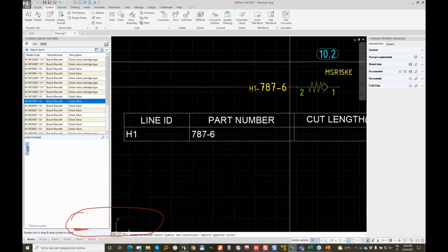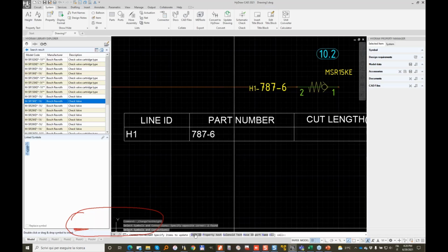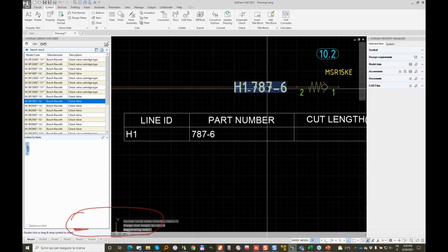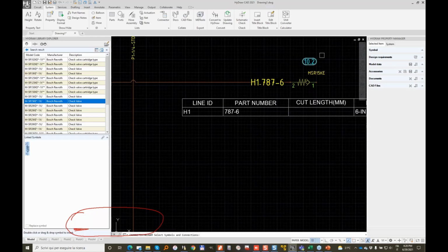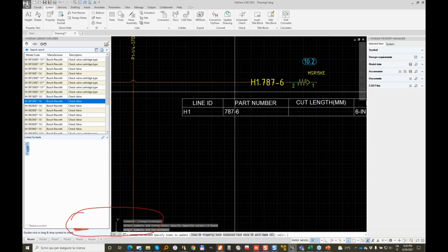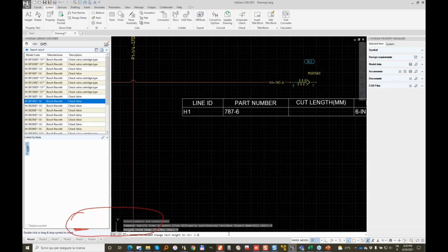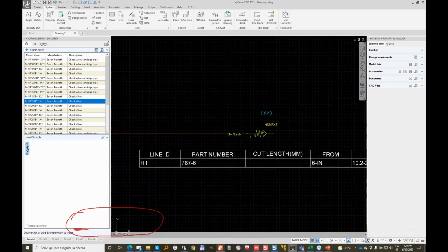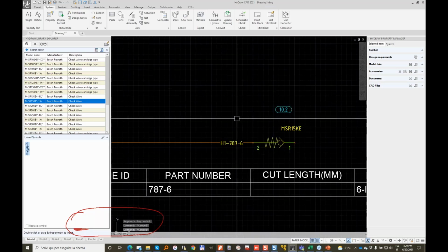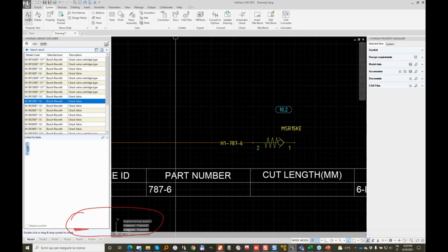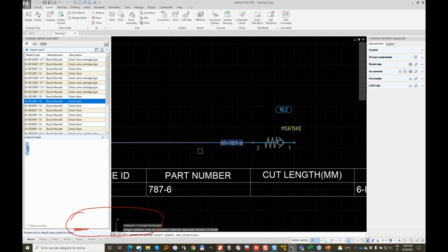Height, we select, and we do all, and make it 4 mm. This will change everything to 4. And at the same time, I can reduce height on a selection, enter. I want to change all and make everything 1.5 mm. And this is making everything small. Any other question? So this is how you control the text height for items in the drawing.